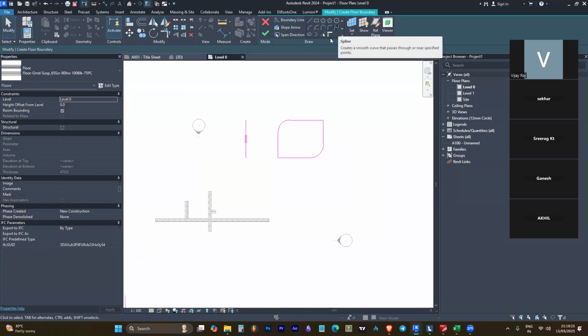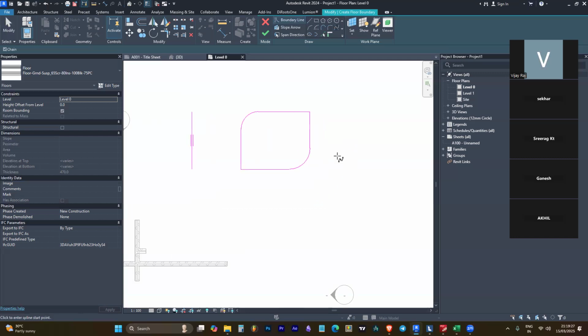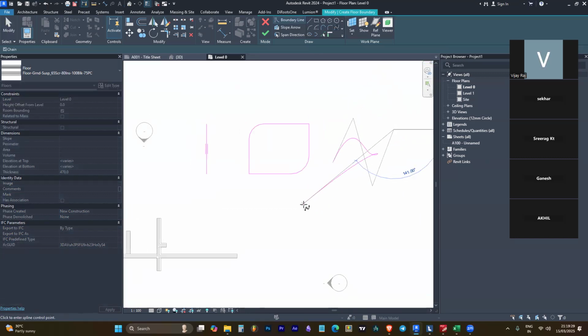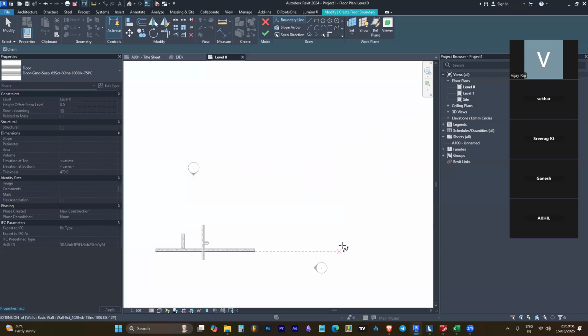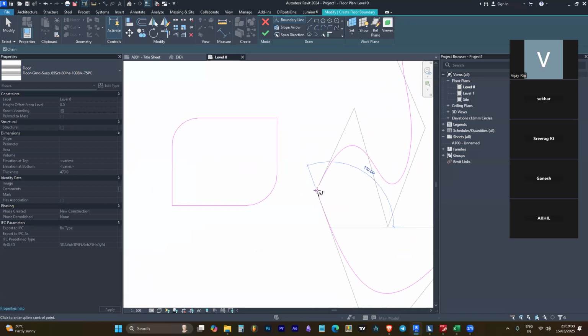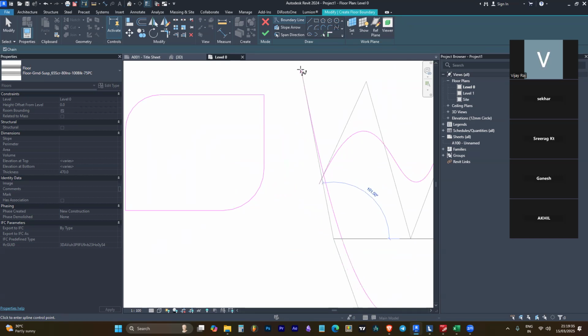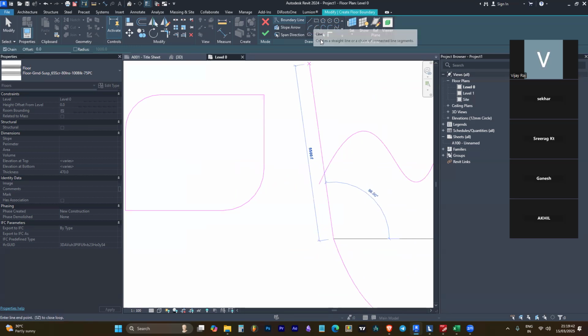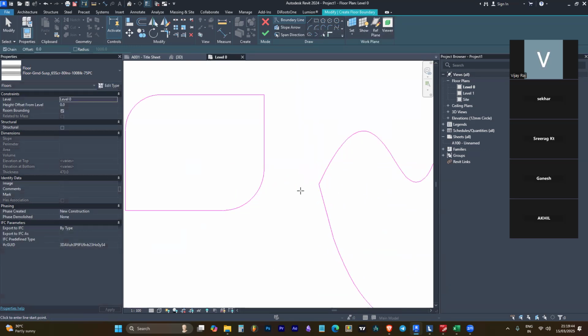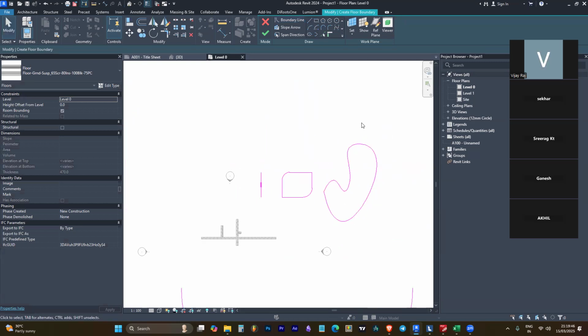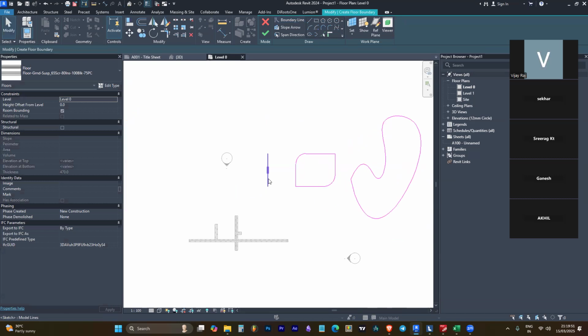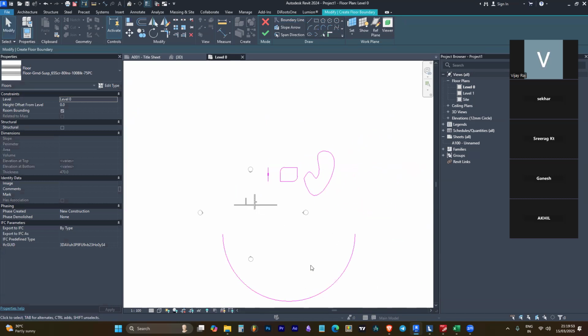And this one is a spline. You can draw wherever you want and go like this. It's always with points, and it is difficult to join at the ends. So try to give the last one with a thin line, only a line. Then only it will get joined. Only a full loop will create a floor, not a single line or an arch like this. If you click OK, it won't allow.